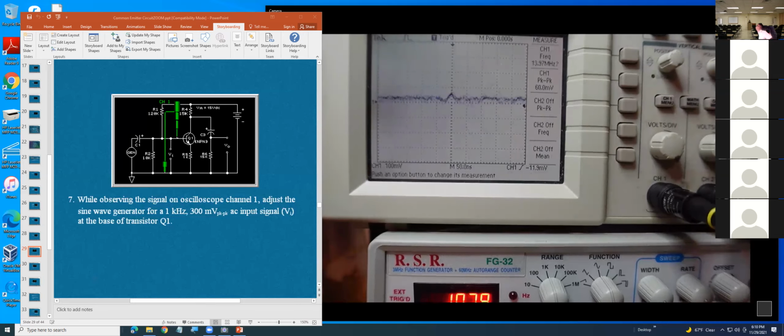Okay, let's see what it tells you. What is the voltage right now? Around 3, right? However, you can see the signal is still noisy, so you must use the cursor. Okay, press the cursor.